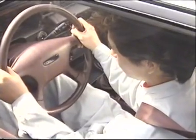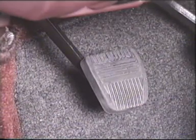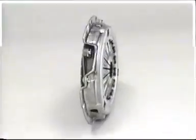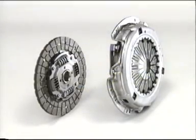If unusual sounds or noises are heard, check to see if they come from either the clutch or the transmission side. If trouble is found in the course of the on-vehicle inspection, it is necessary to remove the clutch cover and the clutch disc for further inspection or treatment.